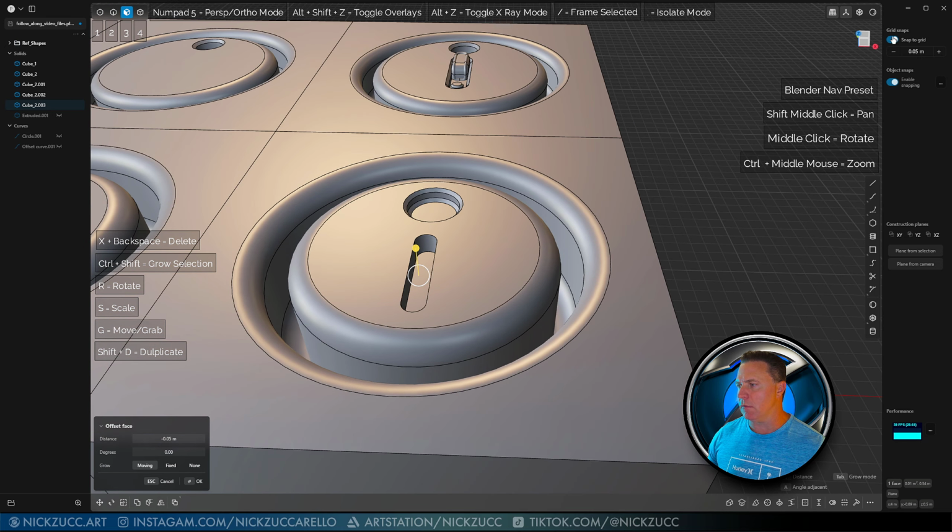Now if I want to inset a circle in here, I can go to the center circle right there, and I should be able to click right on the center. You see this object snapping that's turned on, so that's why it's going to snap right there to the center. Go ahead and click that. And then, actually I wasn't careful enough. I should have snapped to the center down there, but this is okay. I should be able to select this curve with 2, hit Shift I, and then select the body I want to imprint that curve onto and hit OK. So that's a different way of doing it.